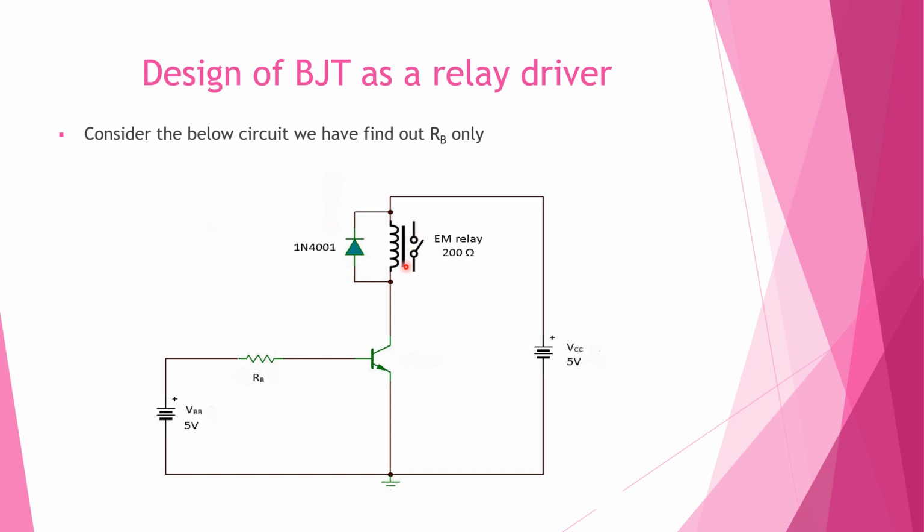Suppose the relay current changes from high current to zero, that is, when the transistor goes from on to off. There will be a big induced EMF, a back EMF here, which will add to the collector voltage, that is some 50 volt or so.